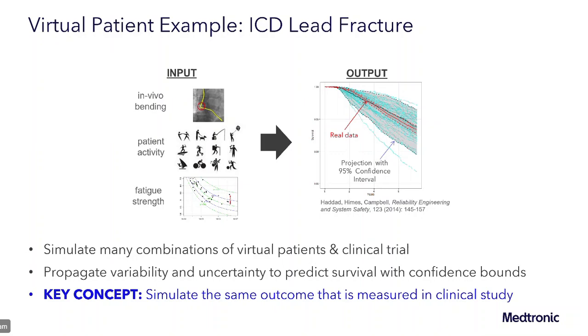Well, the same sort of measurement can be done on these implantable ICD leads. So there's how much it bends, and then there's how many times it bends. You can think about your own examples, whether it's charger cables, or we've all maybe bent paper clips, in a science experiment or just sitting at a desk, and you flexed a paper clip too many times back and forth, and after so many cycles, 10, 20, 100 cycles, then it fractured. It's that same number of cycles that is relevant when we're talking about fracture of these conductors in the ICD leads. So those are the use conditions: how much it's bending and how many times it's bending.